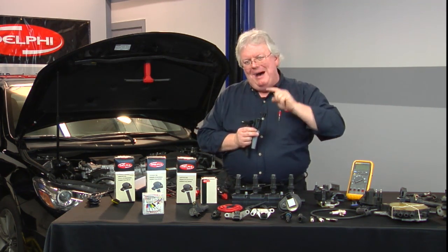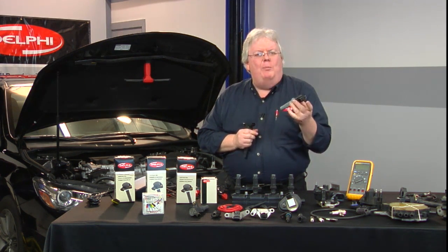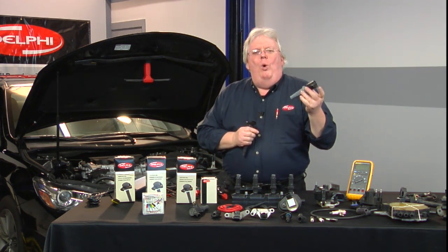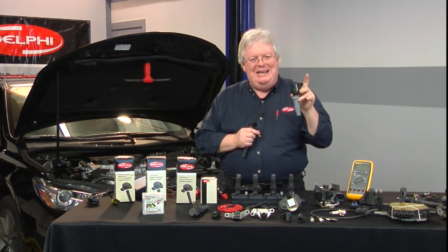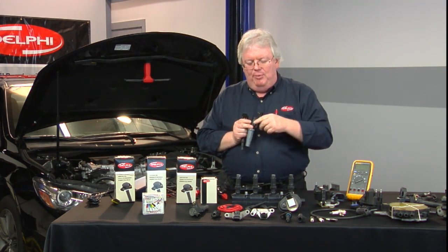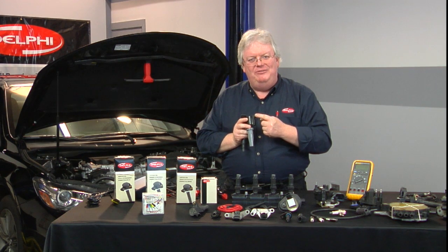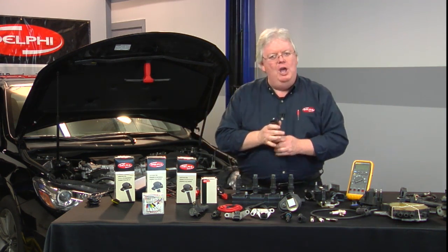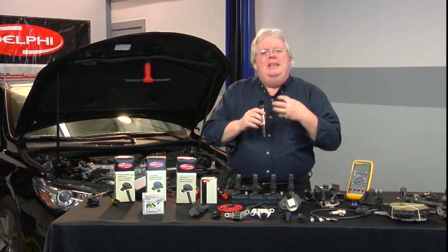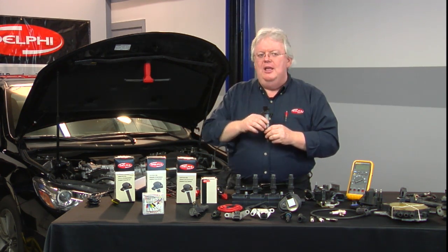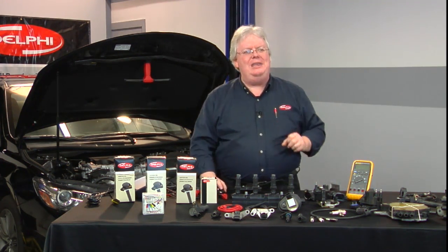Where we don't really have a module here, this is just a coil. This might as well be a '62 Chevy oil-filled tower-shaped coil from the past. Its functionality, that's what it does. Secondary output, primary windings, power from the ignition fuse, a ground supplied by the computer. Or a 4-wire coil with a diagnostic circuit, a feedback circuit. They all pretty much work the same, as we'll get into.